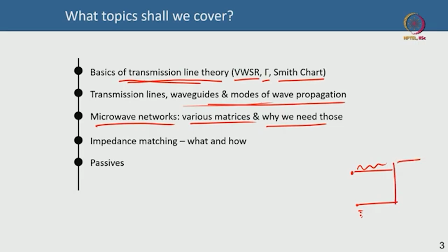So, for instance, this is your gate and this is your source. A signal is coming in here. Okay. So, this is your input port. It is not like the signal is only coming here and this is grounded; it will come and it will go back. Both of them reinforce each other, but phenomenologically you can say one of them is the source, grounded, and one of them is bringing the signal. So, this is a port. Similarly, on the output side there is drain and then there is source. So, the output is between drain and the source. So, it is a 2-port network. So, a transistor, a 3-terminal device, is a 2-port network.